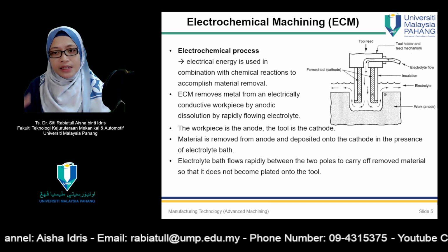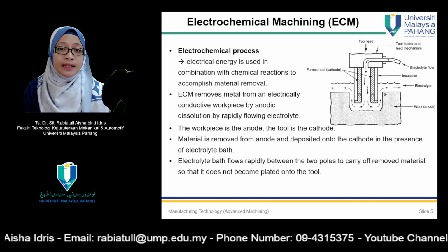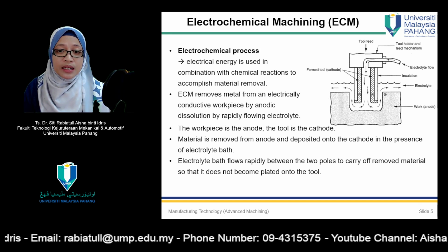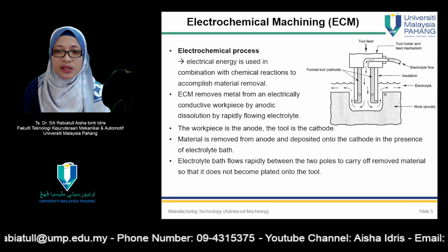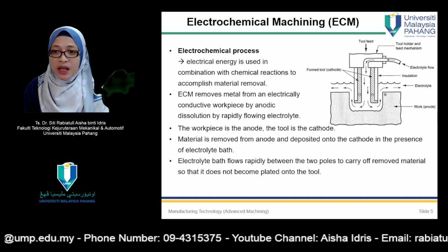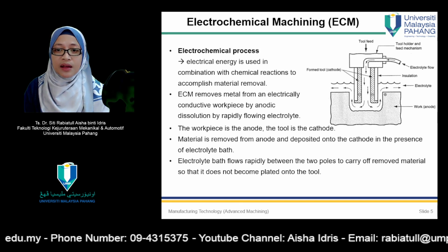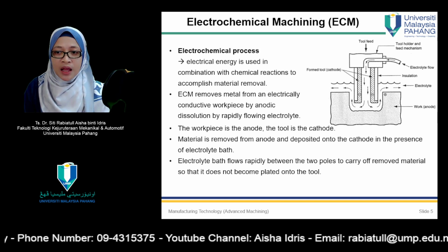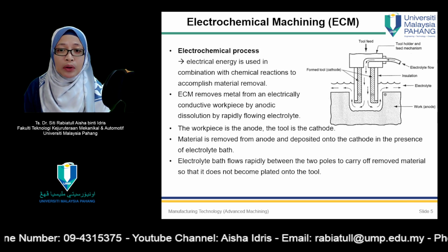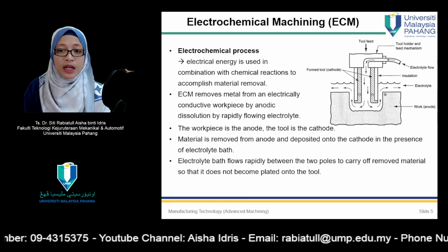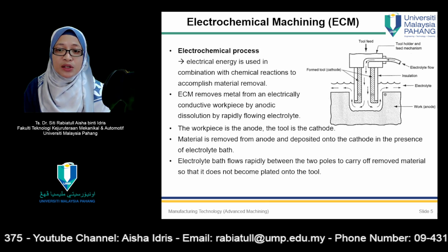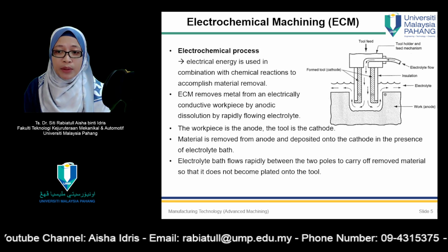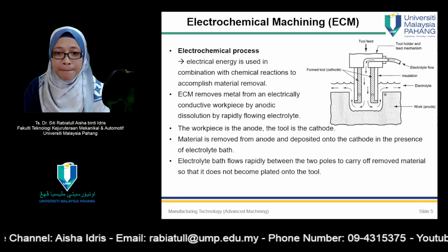This group is identified by the term electrochemical processes because electrical energy is used in combination with chemical reactions to accomplish material removal. In effect, these processes are the reverse of electroplating. The work material must be a conductor in electrochemical machining. The basic process in this group is electrochemical machining, which is ECM.